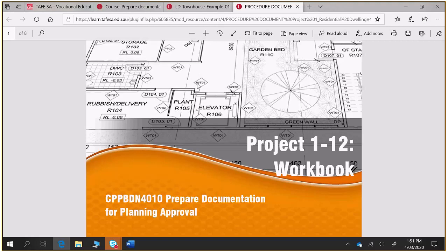Then on your plan or your elevation that's showing the deck, you'll specify specifically steel uni piers, 50 by 50, and blackbutt decking, 70 by 20 or whatever they are. So we just have to do some research and find the products that meet the BAL level. I suggest you do.